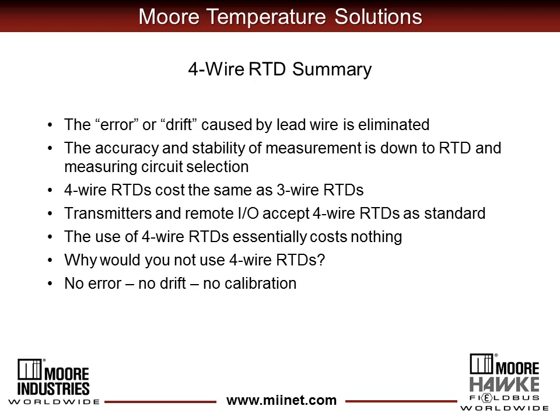In my travels, perhaps the only logical objection to using 4-wire RTDs comes into play when there is a legacy input card that can only accept 3-wire RTDs.